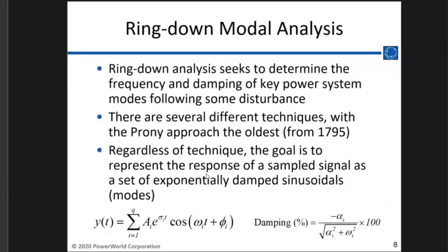The slow stuff that we assume constant, we were just talking about this over break, is let's say you want to run a study not for 20, 30, 40 seconds, but you want to run it out for 60 minutes or something. What would you run into then? Then you start needing to model things like how do the LTCs respond? An LTC is going to look and say, I've got a low voltage. As long as it stays low, or if it comes back within range within 30 seconds, I won't do anything. That's slower, but that wouldn't come into play here for the most part.